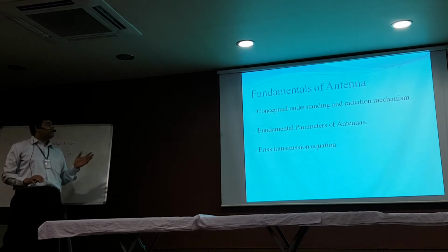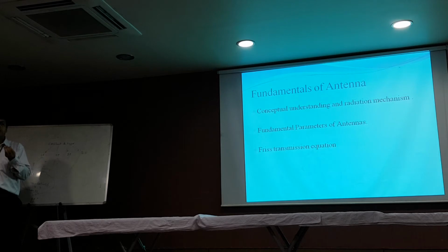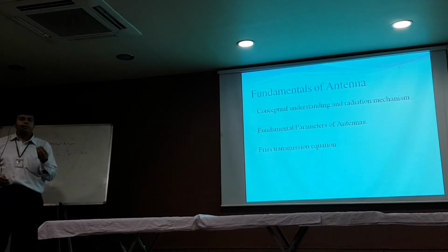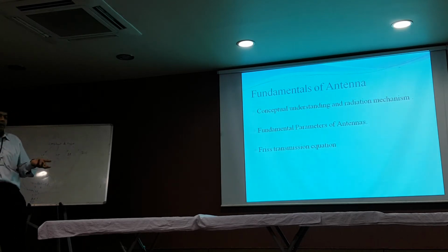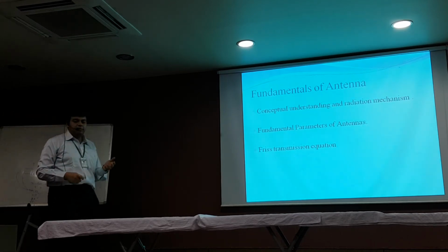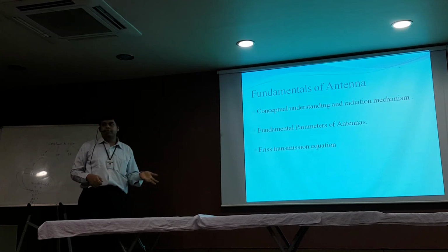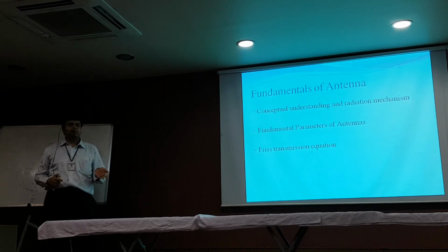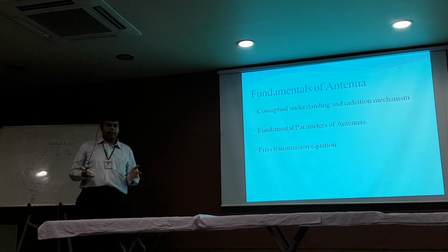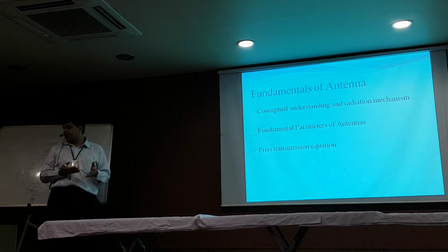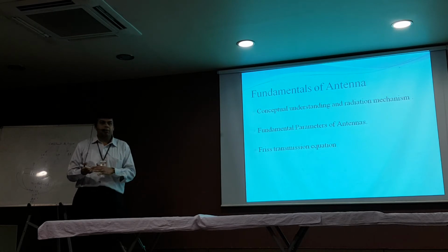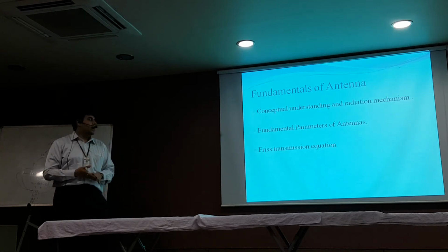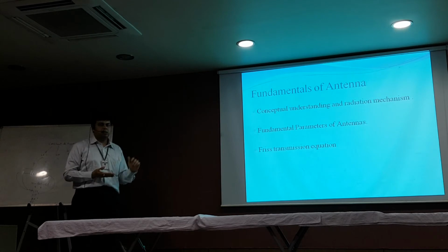So the fundamental parameters of antenna over here, we'll study about the gain. So gain, we know how we define it for the output upon input for the active devices. However, we do not define gain for the antenna in that way, because antenna being a passive device. So there are different definitions of gain for the antenna. So at least I have some 10 to 11 pages of definitions of gain that we can have. Gain with respect to isotropic antenna, gain with respect to directivity, and many more. So those parameters are covered over here.